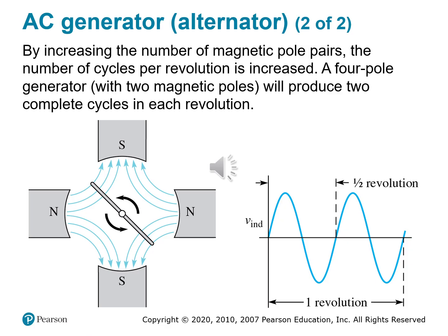So for example, in the US, where we use that 60 Hertz AC for power generation, the generator speed and number of poles are carefully selected so the output waveform repeats 60 times per second. More poles means you can generate higher frequency without spinning faster. A huge advantage for large machinery. So it's not only that it's a smooth sine wave, it's also scalable.